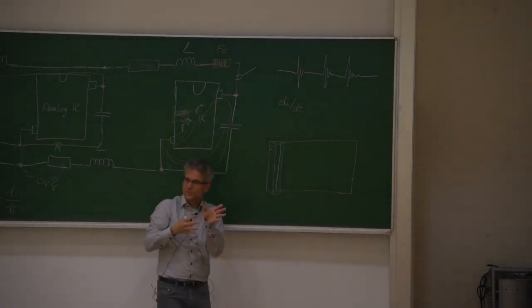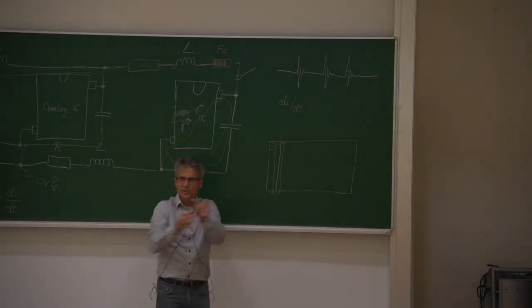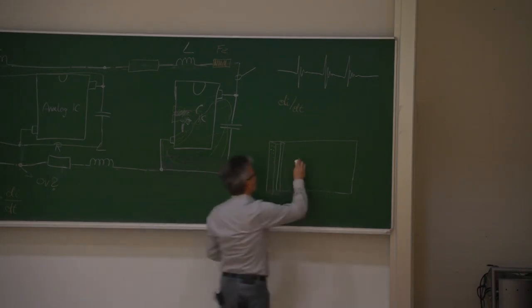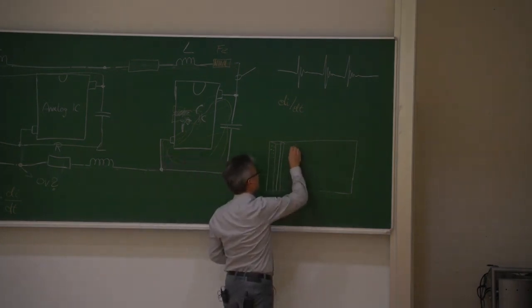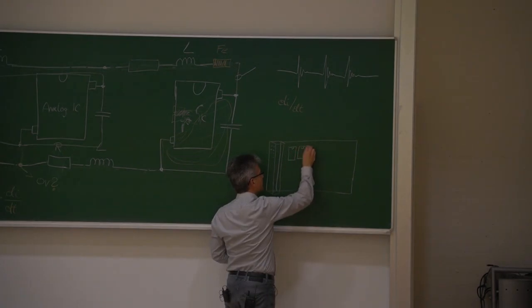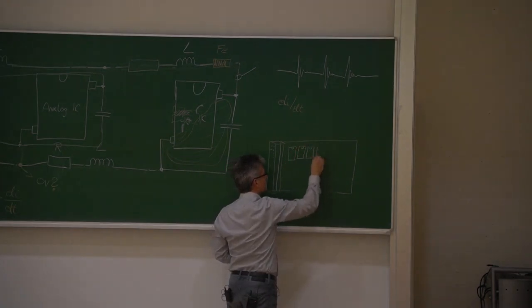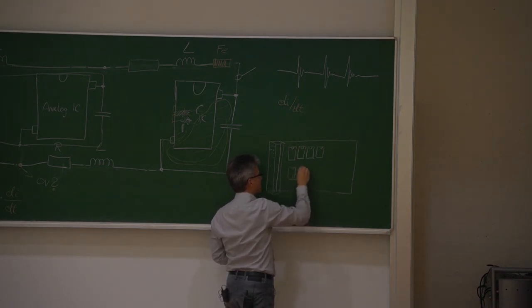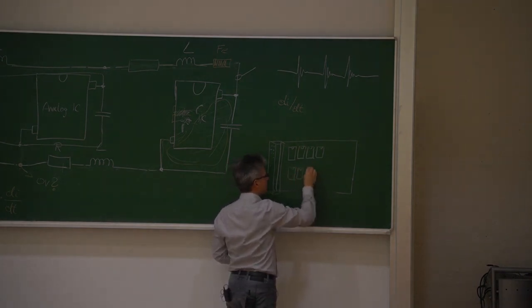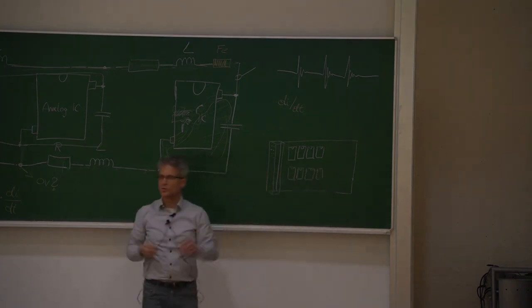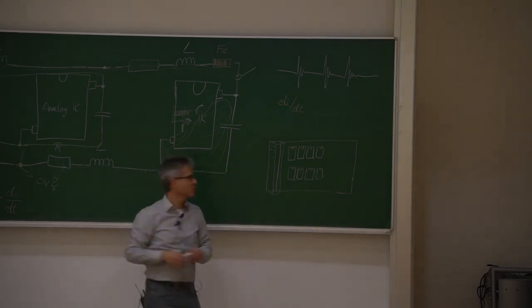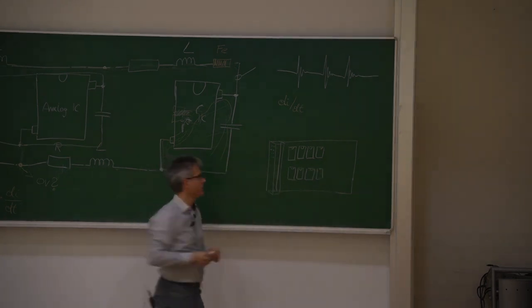So imagine that there is a printed circuit board that is stuck into a kind of back plane. And then on the old printed circuit boards, they had one IC next to the other to place as many digital ICs on one printed circuit board as possible. There were no multi-layer printed circuit boards. They very often had only 2 layers.